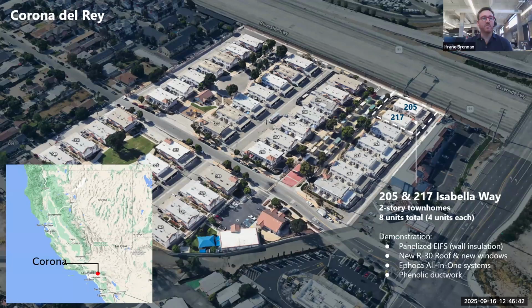That's right, Ephraim. What kind of steps did you take to mitigate moisture inside the buildings after you sealed everything up tighter than it was prior? Yeah, so that was part of our investigation, certainly for the Vera Cruz project, because we sealed off the existing vents in the attic.